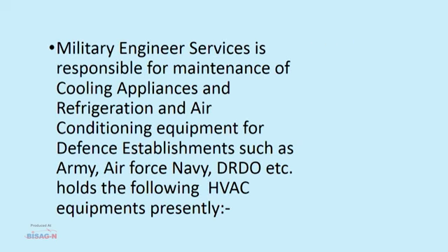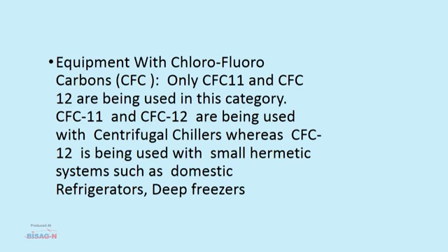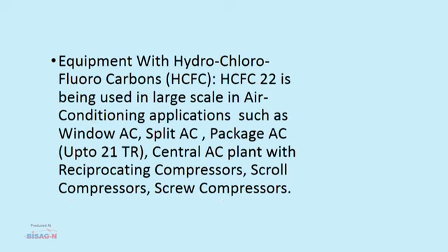MES, Military Engineering Service, is responsible for maintenance of cooling appliances and refrigeration and air conditioning equipment for defense establishments such as Army, Air Force, Navy, DRDO, etc., which holds the following HVAC equipment presently. Equipment with CFC, chlorofluorocarbons: only CFC 11 and CFC 12 are being used in this category. CFC 11 and 12 are being used with centrifugal chillers, whereas CFC 12 is being used with small hermetic systems such as domestic refrigerators, deep freezers, etc.